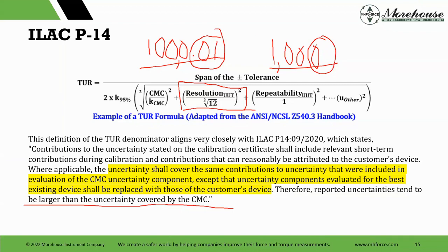Why read it out to extra precision or decimals? It can be a perfect instrument. I applied 1,000 pounds and I know that I'm good to 1,000 pounds. Really wrong, and wrong in a lot of ways. But one of the biggest ones is we're not accounting. If we do not account for the contribution of resolution, we're really not taking risk into account at all. We can just set things to be perfect.